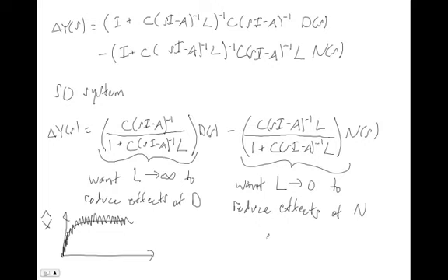When you hear the term Kalman filter, all a Kalman filter is is a choice for the gains in L. A Kalman filter is our perfect observer gains, and it's going to be perfect assuming stochastic models of our disturbance and our noise and our initial estimation of our initial state. So that's what a Kalman filter is. It's the optimal choice of these gains L, just like an LQR controller was the optimal choice for the gains K under certain assumptions about our system.